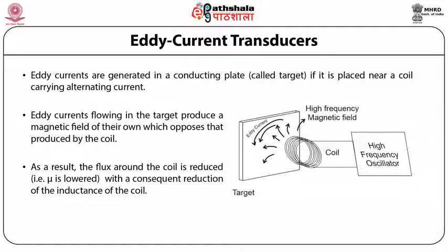So this effect depends upon the distance between the target and the coil, because the nearer the target is to the coil, the higher the eddy current and the lower the inductance, and vice versa.